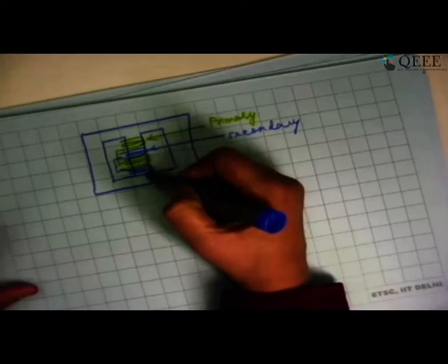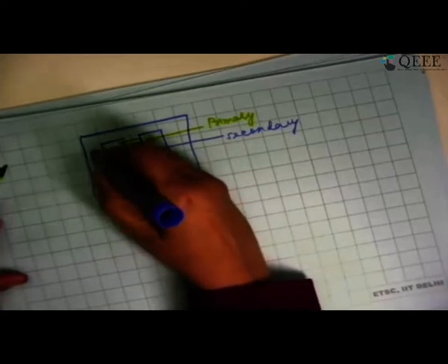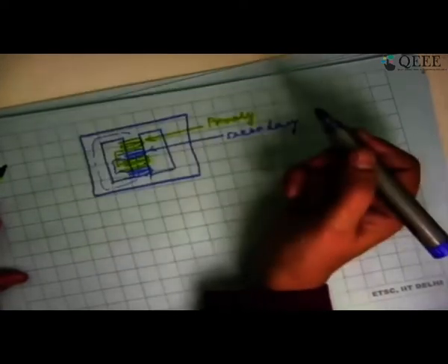You can see that they are arranged one after another like what we do in a sandwich. So first is primary, then secondary, then again primary, then again secondary. So all of them are arranged in a sandwich fashion. When they are arranged in sandwich fashion, if a flux is going like this, the flux necessarily has to link both primary and secondary. There is no other way out, so there is hardly any leakage. So this is essentially sandwiched winding, when you are arranging one after another or one above the other and so on.